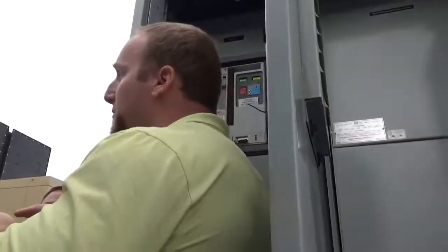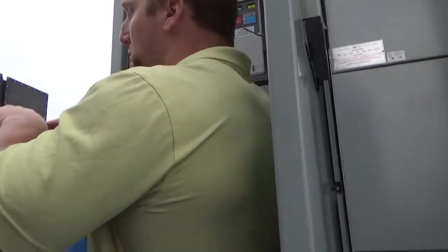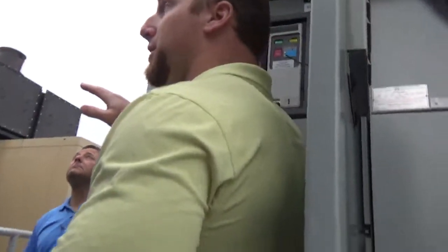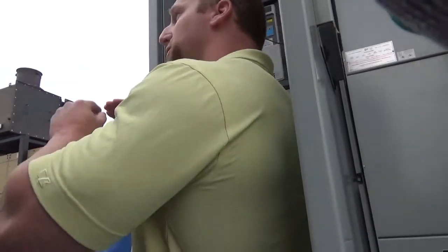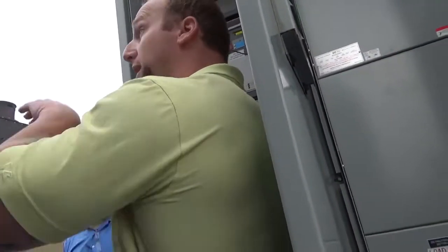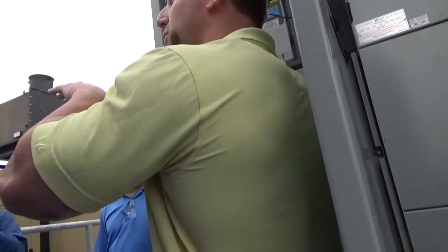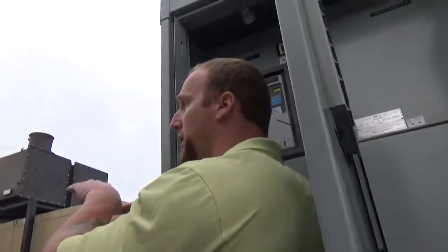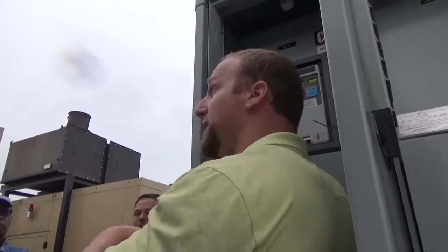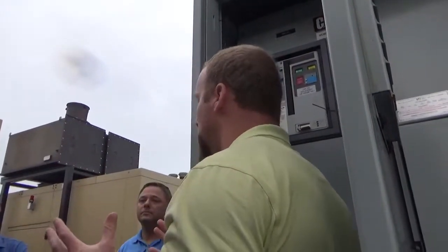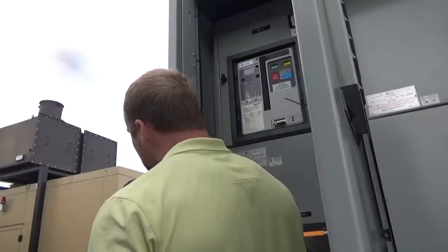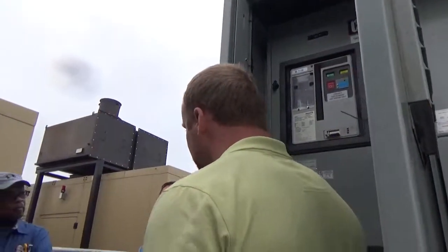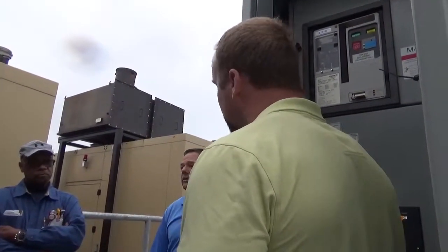Gen demand and load shed kind of work hand in hand with each other. So if you have a scenario where you drop a gen off the line because of your gen demand scenario, and then it starts realizing, okay, I need another gen, but I could load shed, the percentages are far enough apart from each other where you're going to add another gen before you load shed. Load shed will normally only come into play when you have both gens online and you're exceeding your maximum kW that you have available. And that's really nice if you're doing maintenance on one generator. If you have a power outage, you won't overload the one generator.